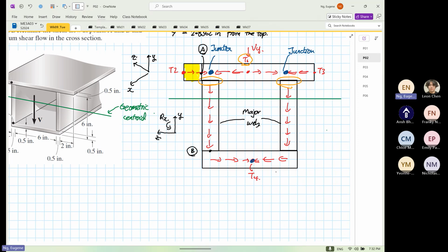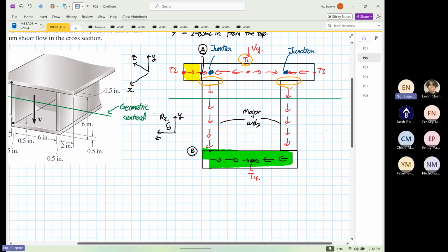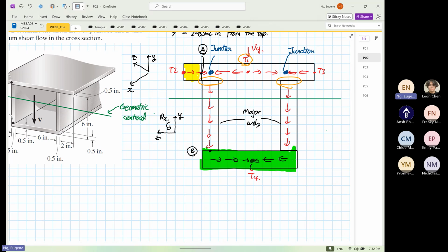Okay. Whereas B, the area to consider, right? The area to consider is you have to consider this entire area over here relative to the closest what? Terminal. Yes or no? And it's going to be a box beam, right? So that's where we are going to focus to calculate our first moment of area. As you can observe by now, right? Calculating the first moment of area in thin wall analysis is so much dependent on your design of your shear flow.